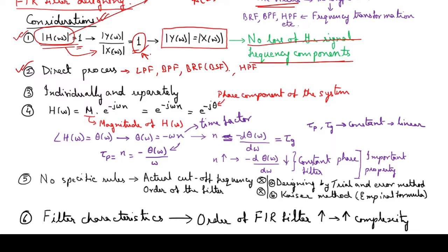So while designing IIR filters, we initially design a prototype low pass filter, where the cutoff frequencies, the roll off, and all these things are decided. All the characteristics of the pass band frequency response and the stop band frequency response are decided.